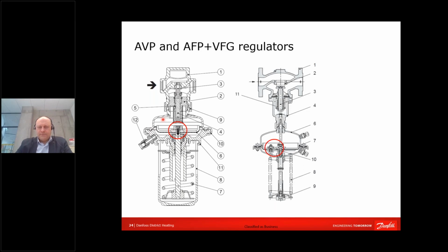Larger controllers are constructed almost with the same scenario: valve, setting element. What should be reminded is that these valves are made so that the sealing is in the membrane. So when you are installing your system and when you are not attaching the membrane, the valve is open to atmosphere, so water can go out. Please consider it during installation.